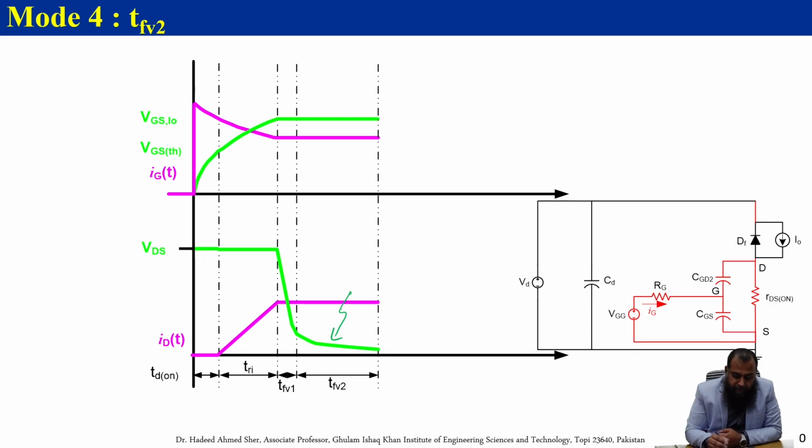This ID is fixed here, and because the voltage across the VDS is very low, we are right now in the falling voltage 2 state. And after this given state, you can see that this dependent current source is now replaced by an RDS on, because this RDS on represents the behavior of a MOSFET in an ohmic region here.